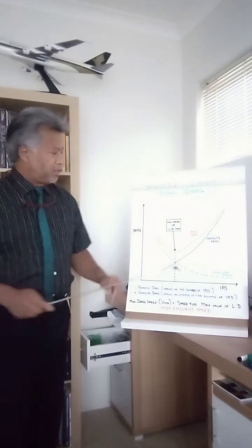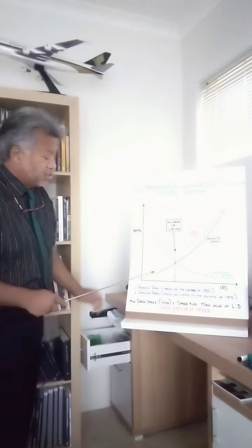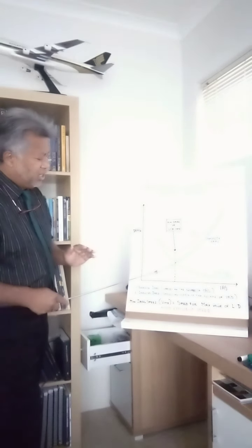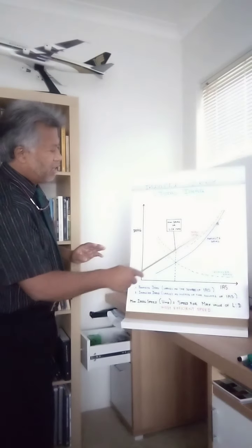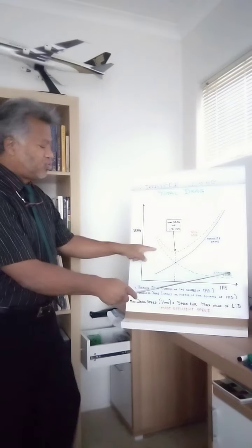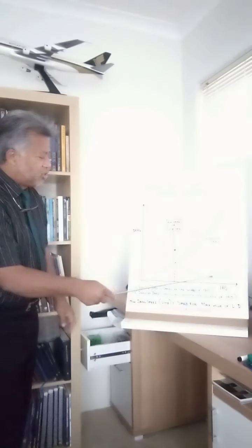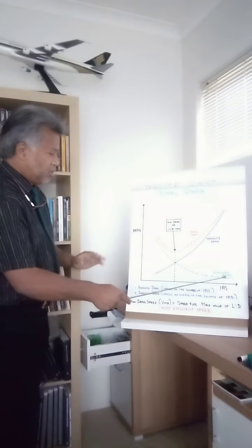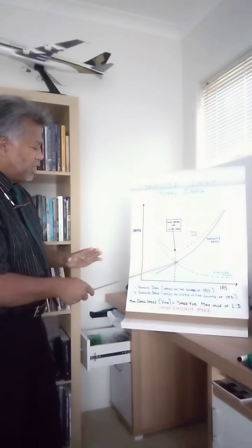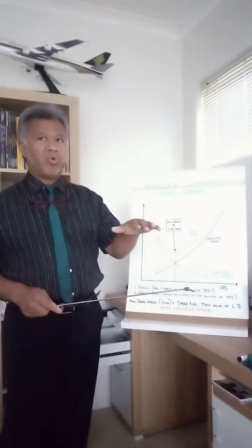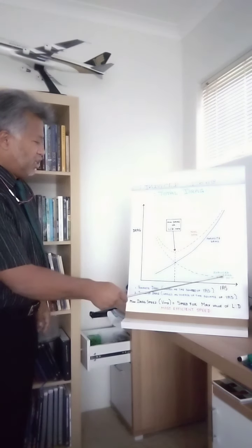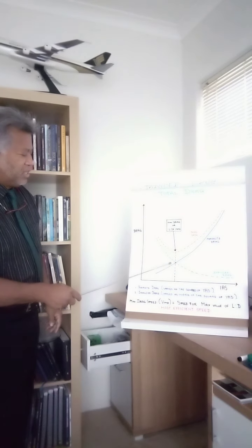If we plot the parasite drag, like we said, as the airspeed increases, so does the drag. Whereas the induced drag decreases if you increase the airspeed. All right. So if you go slower, in order to go slower you use lifting devices and increase your angle of attack, and the induced drag becomes greater at lower speed.